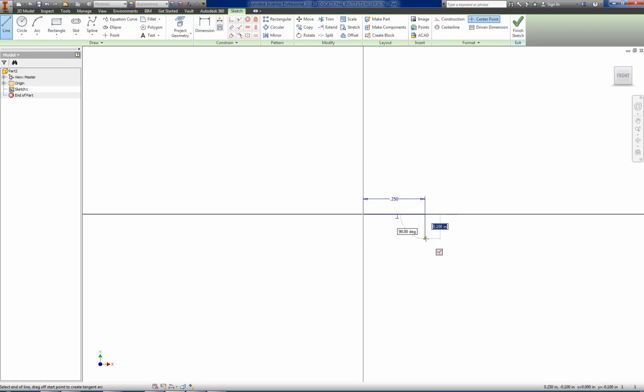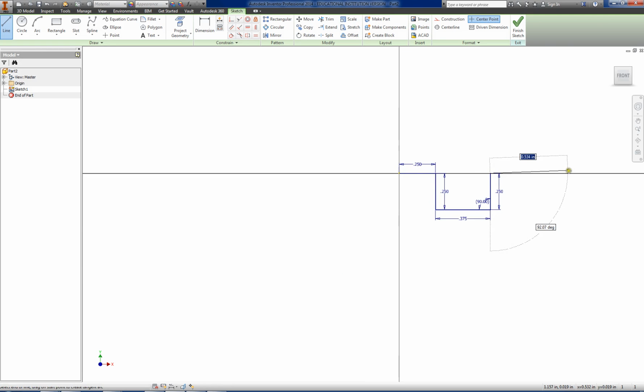It's important that when we start doing this, we start from that origin point because it's going to help constrain it. Now in my sketch, I actually went through and I did some half squares. So that's where I'm getting that extra 1/8 of an inch. But notice as you go through, we want to get our position set. So I'm kind of pulling it, and if you see the icons that are showing up, you have that little two lines. That's the parallel constraint. So that's locking them parallel.